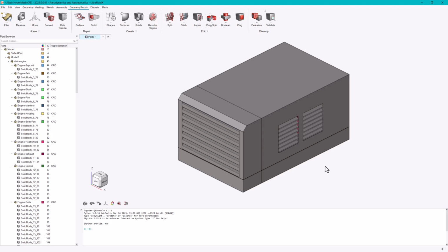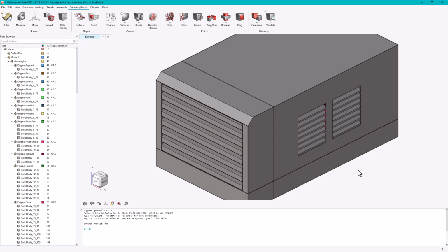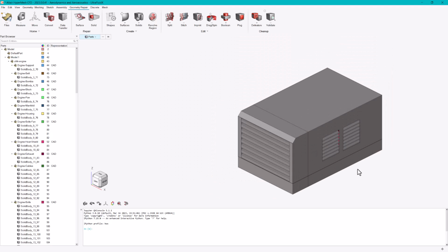Then we can start the workflow with the critical flow parts. In this example, it's basically the fan and shroud. Both parts need high-resolution elements in order to describe the curved solid parts accurately and capture the flow around them accurately. Since UltraFluidX post-processing uses surface elements to show surface results like pressure and wall shear stress, we also need more uniform mesh for those parts. So first we isolate the fan and shroud.